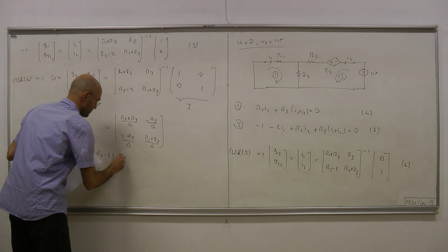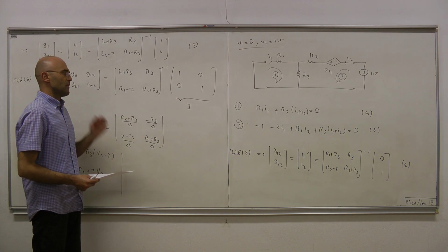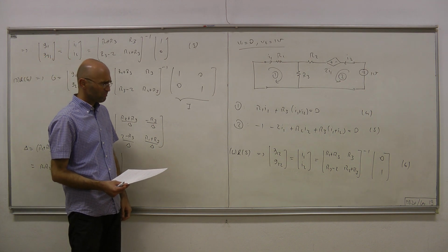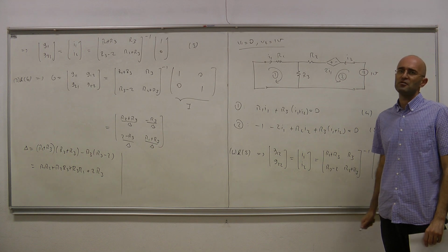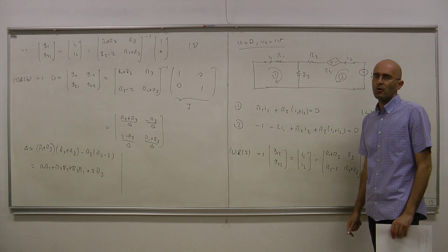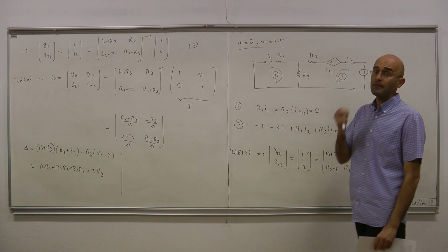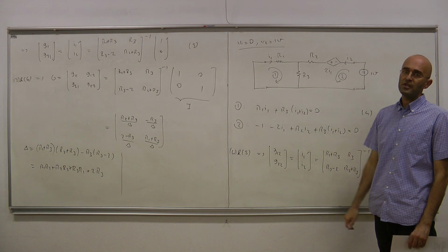So we obtained the conductance matrix in a little bit longish way, because we already had the resistance matrix, and if you can invert that resistance matrix, that automatically gives you the conductance matrix. Likewise, if you have the conductance matrix already, by inverting it, you can obtain the resistance matrix representation, if the inverse exists.